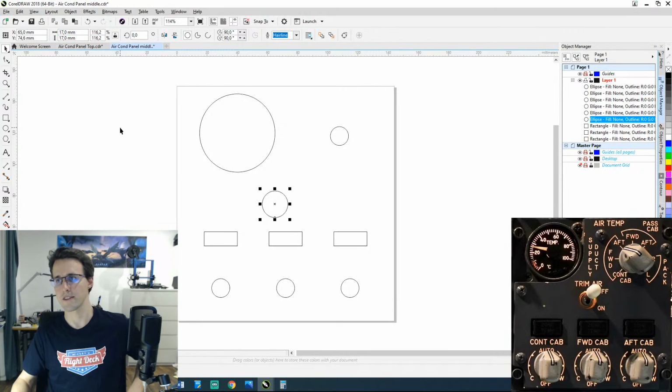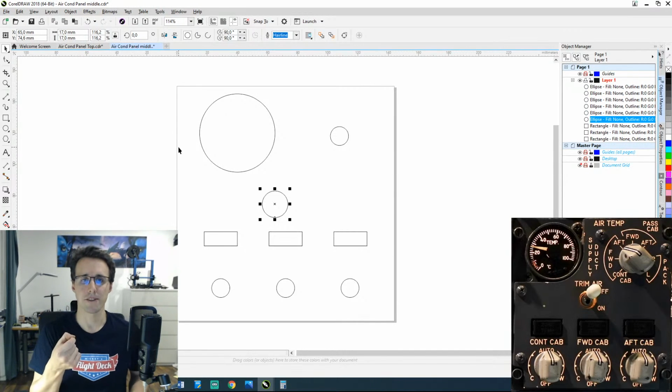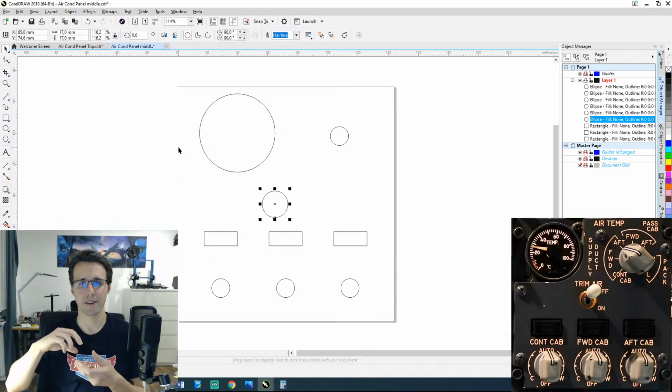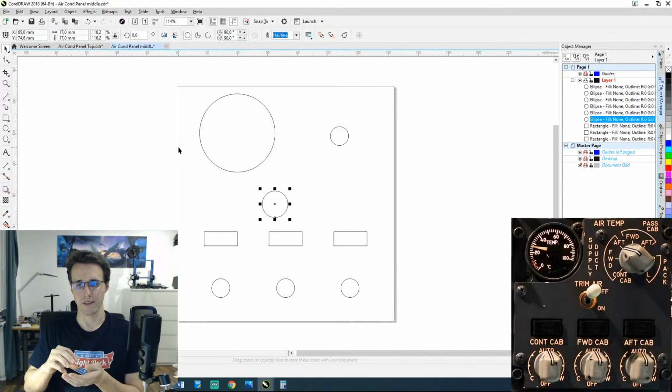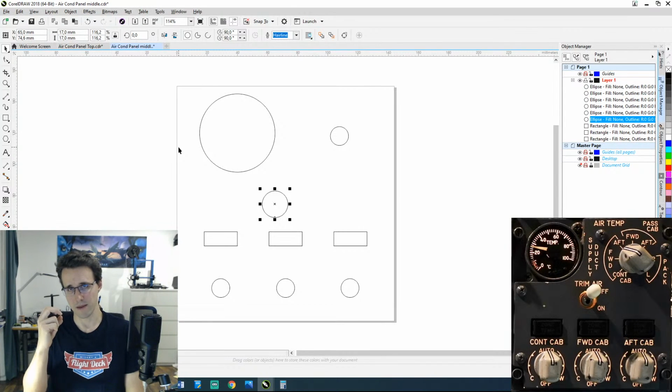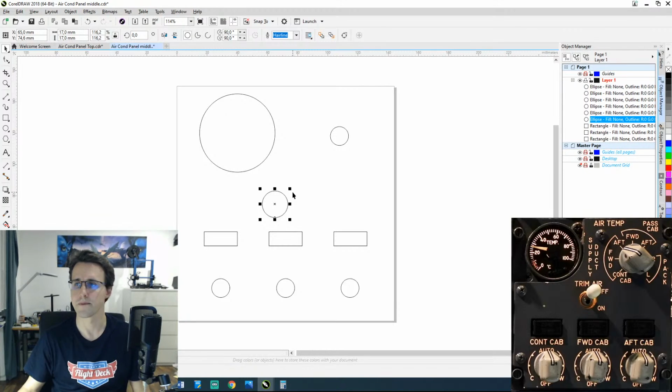I've said this before, because the switch has a shaft of 12 millimeters, but then there comes this nut that fixes the switch to the bottom panel, and this has an outside diameter of 17 millimeters, maybe a little bit less, but to stay clear I use these 17 millimeters, and it is covering this nut.